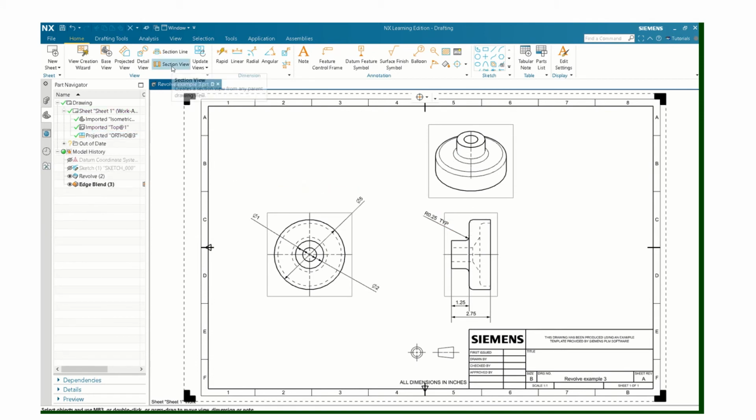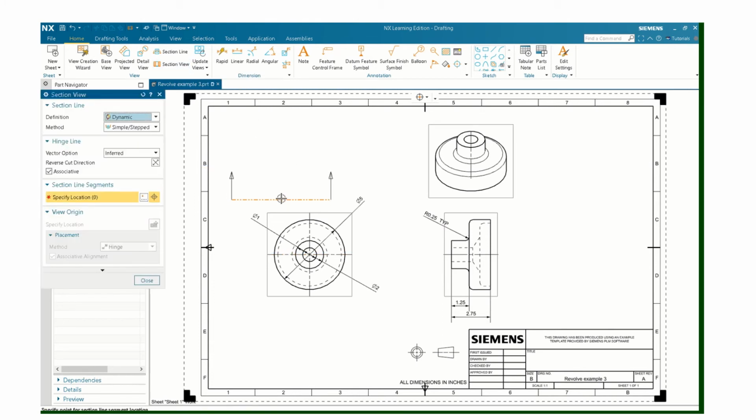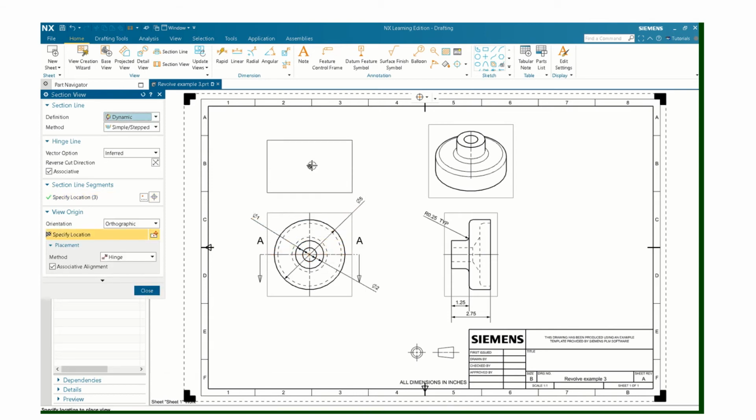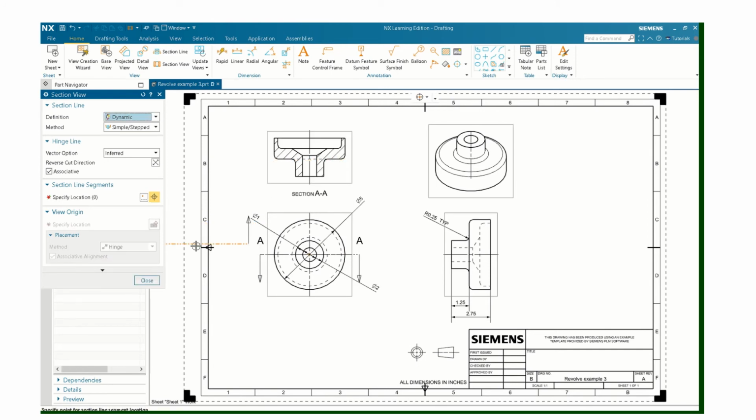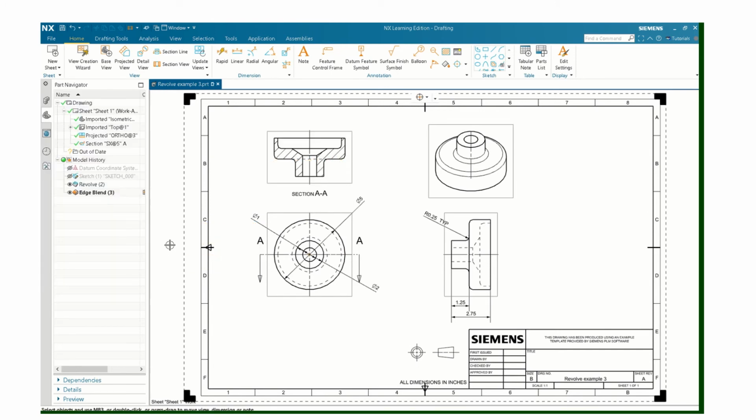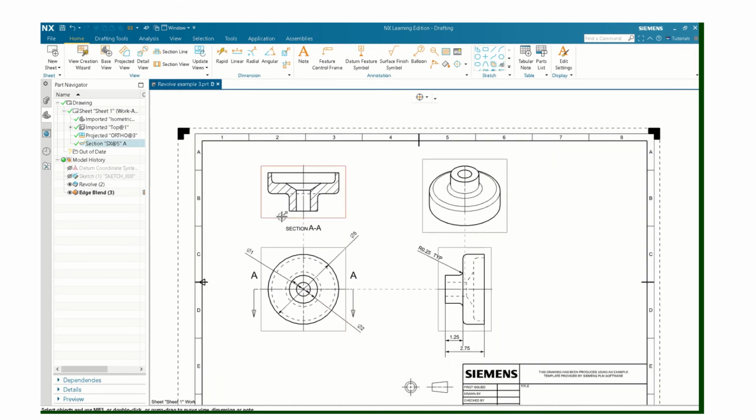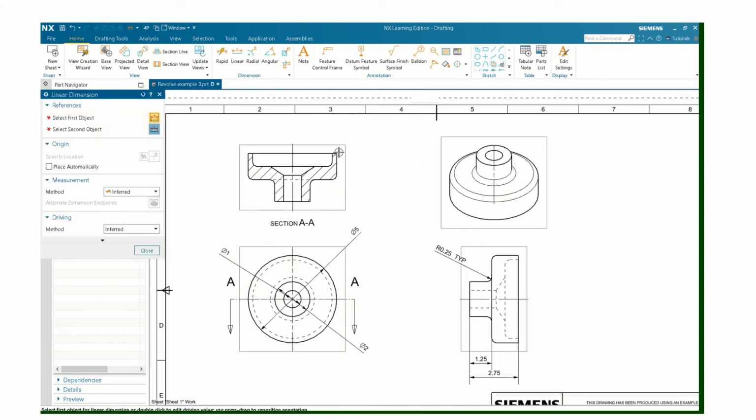So up here to section view, and you'll see it'll have the section plane lines right there. So that's easy enough. Just click on that center point, drag your cursor up, and that'll create the section view for you. So it's easy enough. Now let's watch where our dimension lines go. So now I got a perfect place to call out, for example, the depth of that.